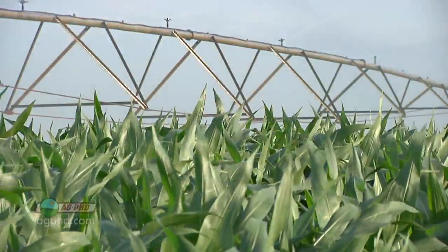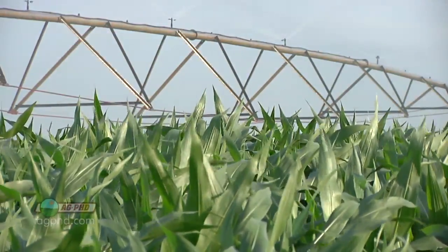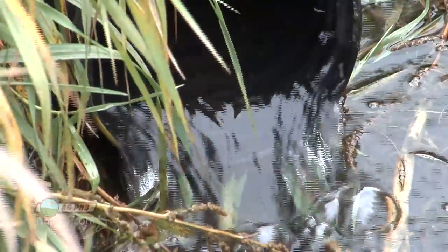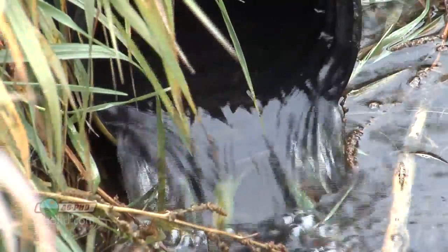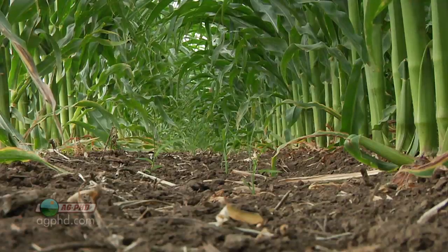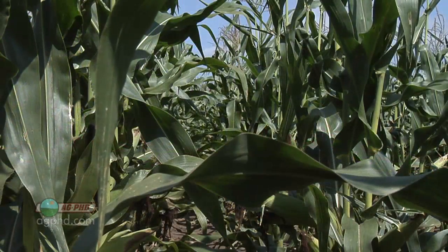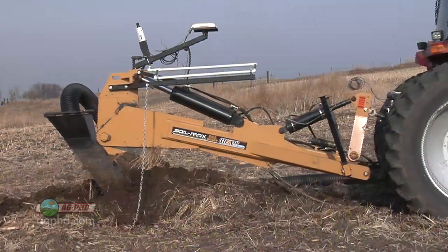Well, the problem is, are you irrigating perfectly across every single square foot of your field? And rarely is that answer going to be yes. It's very easy to overdo it, at least in some spots in the field. Well, if you have a little too much excess moisture flowing down in your tile line, get that out of the field, and also keep in mind salts are very leachable. So if we have good drainage in the field, those salts are going to flush right through in a lot of cases. So we don't have the high pH issue. We don't have the high salt issue. This is a big thing that we want you to think about.